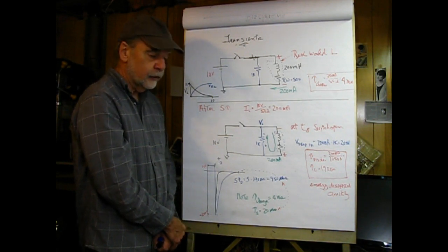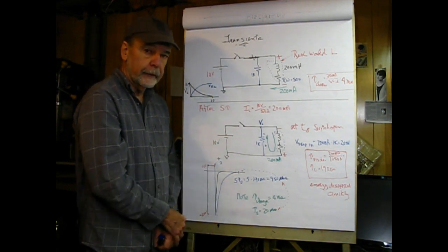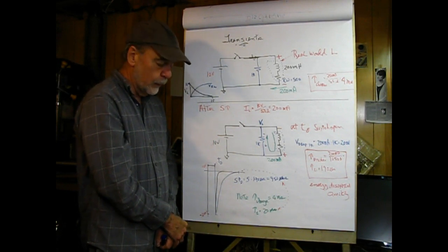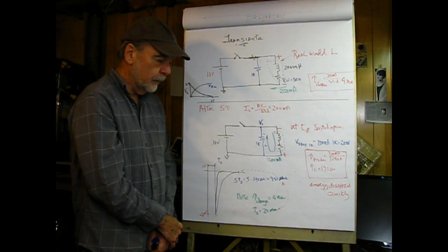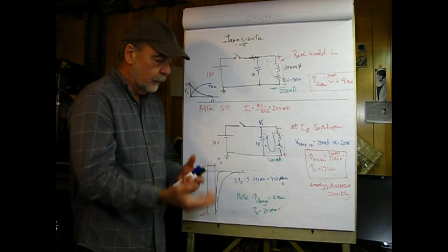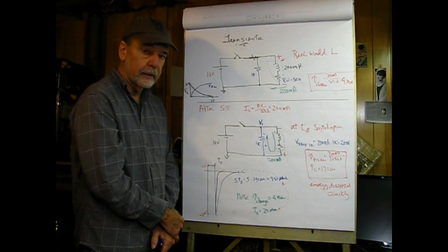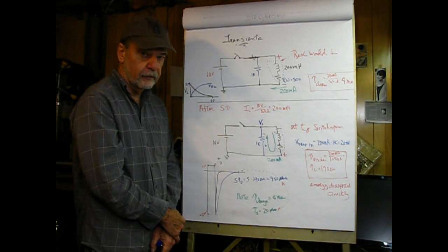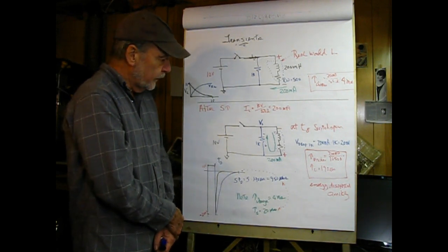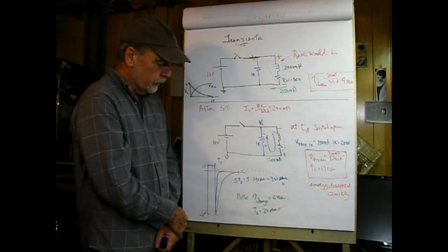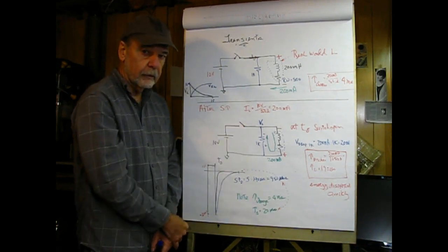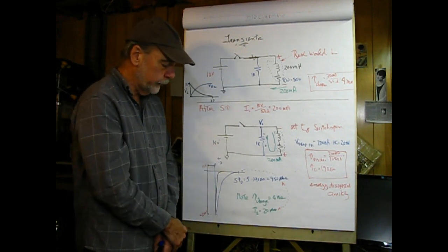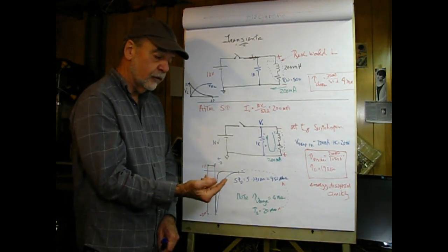based upon charging an inductor, opening a circuit, and letting the discharge path produce a really high voltage, which causes a spark across the electrodes in your spark plug, which hopefully is around a gas-air mixture favorable to ignition. And it's not 100% guaranteed that a spark is going to light off a cylinder. So that's the transient nature of induction and inductors, and if I were to have my finger across this, when I open the switch, I would definitely feel it. The 200 volts would definitely be able to penetrate the dryness of my outer layer of skin.